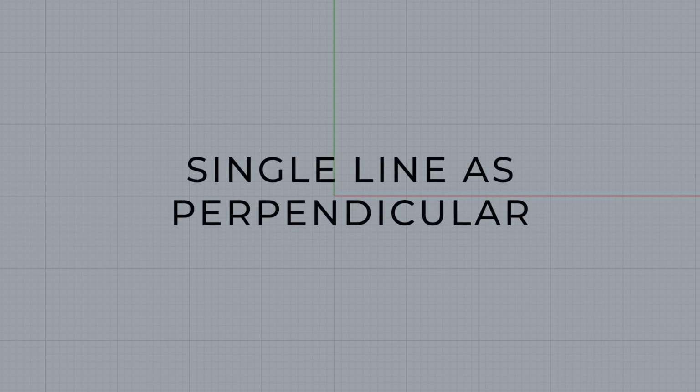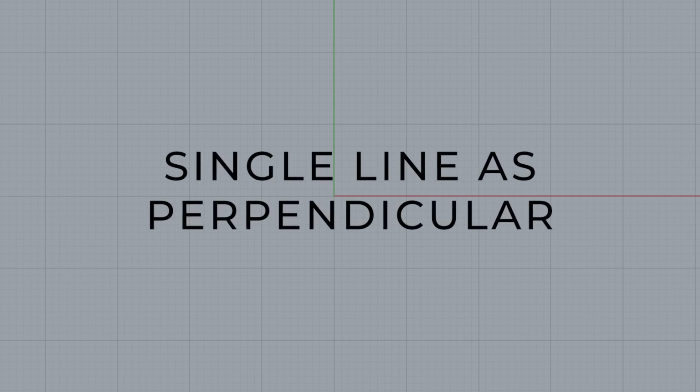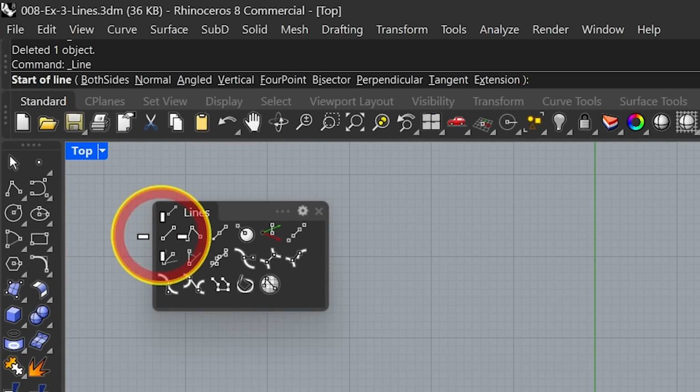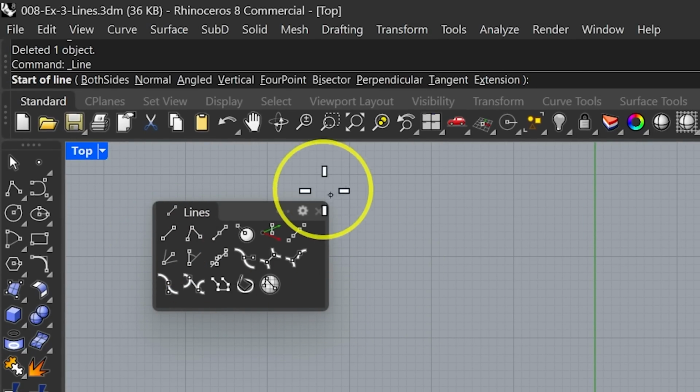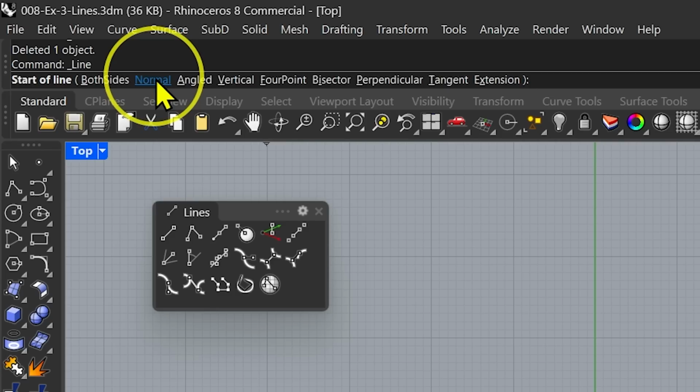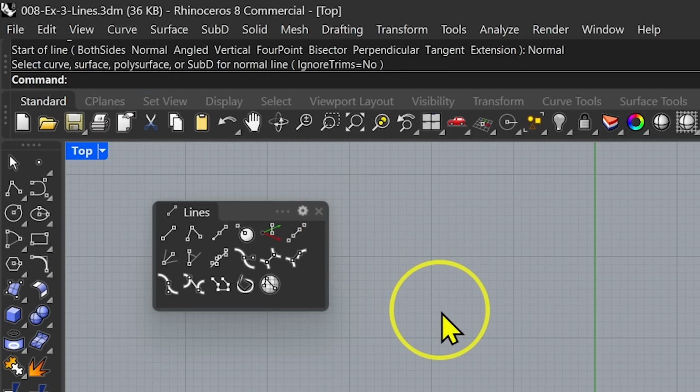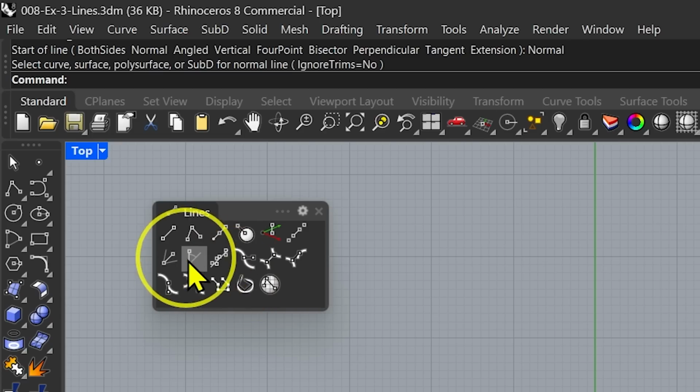Next, I will show you how we can make a single line as normal or perpendicular from any curve or surfaces. Let's activate the single line again. And before starting the line, select normal from the options. You can also type N and hit spacebar or enter to activate the same. Next, it will give various options from which I can make the perpendicular line like curve, surfaces, polysurfaces, or even sub-D models. For now, I will show how we can make a perpendicular line from a curve and surface.